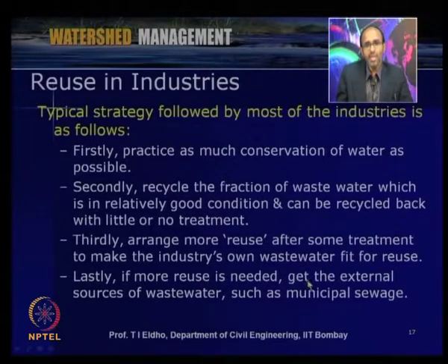And then finally, as we discussed for some industrial plants like RCF in Mumbai, if more reuse is needed, get an external source of wastewater, say from the municipal corporations. The municipal sewage can be obtained. Some industries in places like Mumbai and Chennai are doing this. They buy the wastewater from the municipal corporations, give appropriate treatments, and then it can be reused. That is how reuse in industry is concerned.